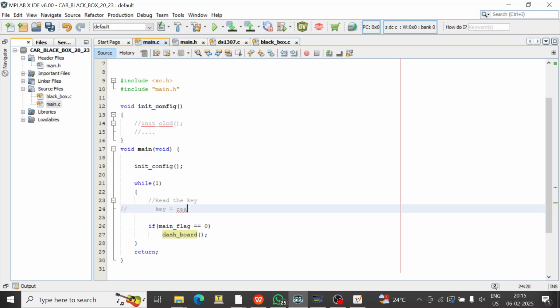It will block your entire code. Entire instruction will be stopped for that 5 seconds. You should use non-blocking only. You should not stop the code execution. Instruction execution should not be stopped. You need to use non-blocking only everywhere. Okay, don't use blocking ever. Fine.